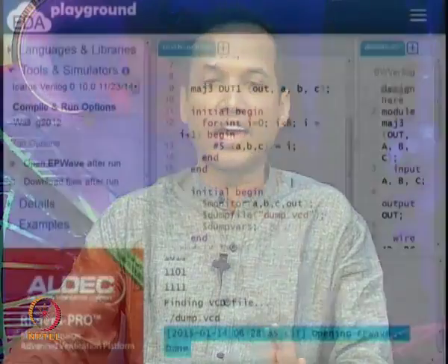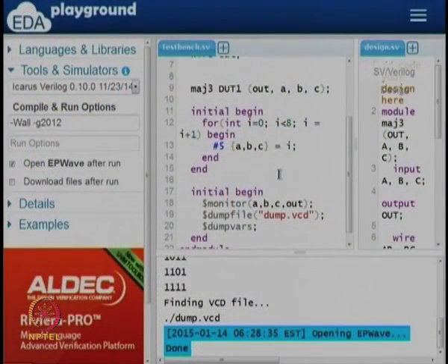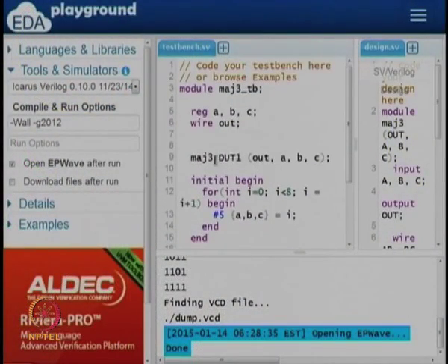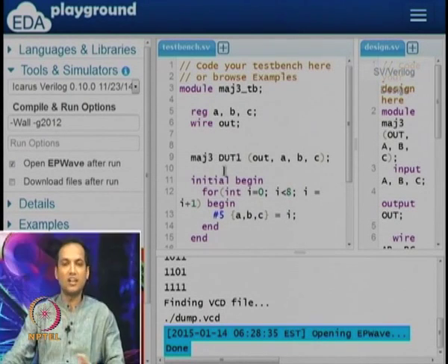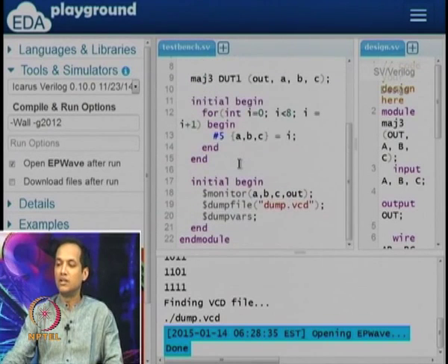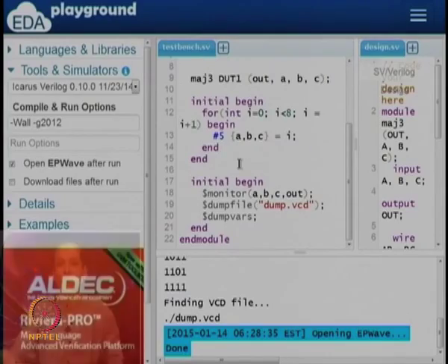So it is already taking care of 3 inputs, iterating through them and so on. All you need to do is change the circuit that you want here. So whatever you call here, let us say module XOR 3, if you call that here, you have to put XOR 3 here, rest of it can remain the same. So if you feel a little more confident, I will suggest that you go and come up with your own problems and write your own test benches and so on.